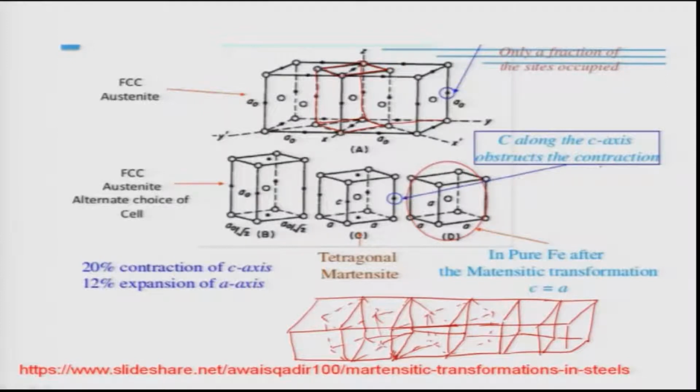The only thing you need to know is that it basically happens like a pack of cards in steel metallurgy. It's very easy to do this transformation. That's why simply by taking a steel, heating it at high temperature and quenching it into water, you immediately transform it to martensite. It's very easy, and this is the reason why it happens.